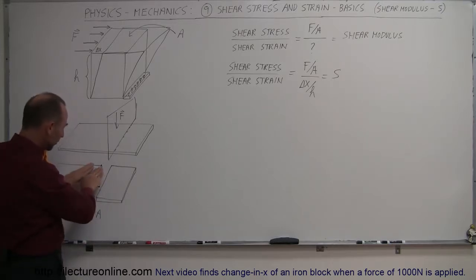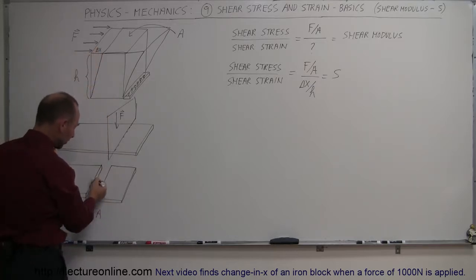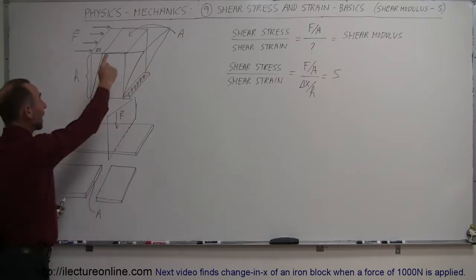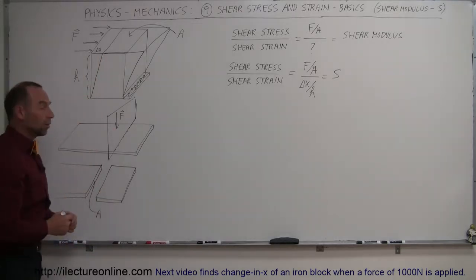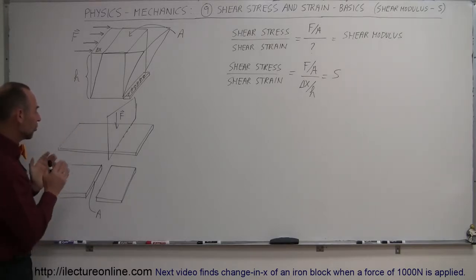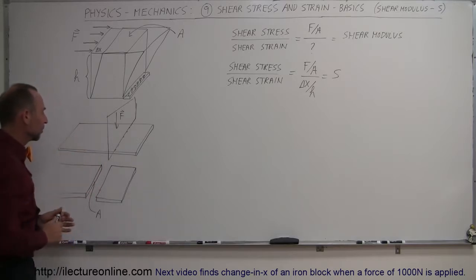Notice that what you're going to do is, when this is still attached, you're trying to push this material away from this material, so you're going to try to stress it in this direction. So it's basically stressing it like that, and so the cross-sectional area of the cut becomes the area here. So the important part of an industrial application like this is to just understand how much force will be required to go ahead and cut a piece of material off.